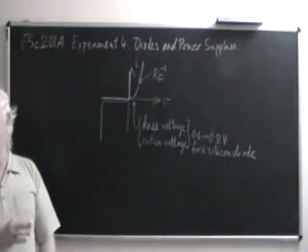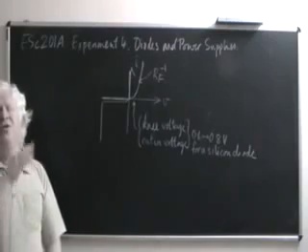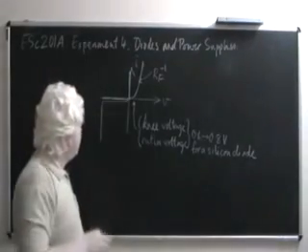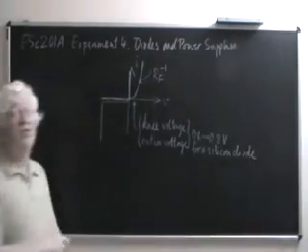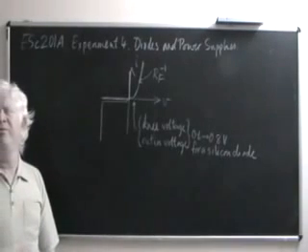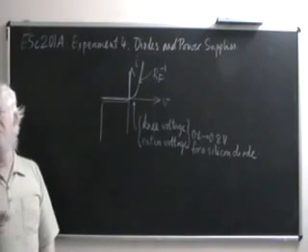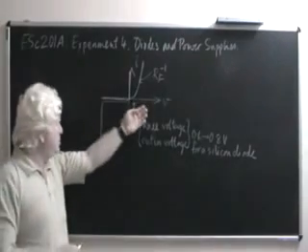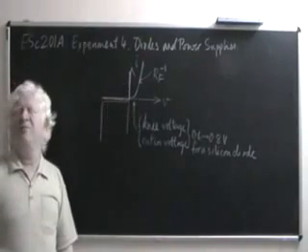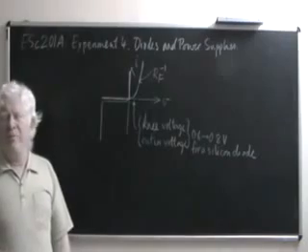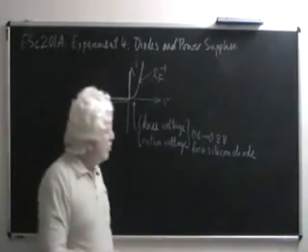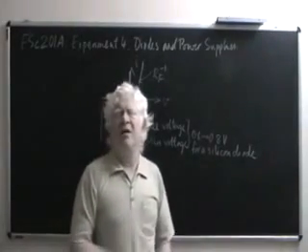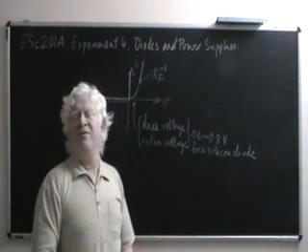Now, what you will do in the laboratory is to rig up a circuit which will plot this characteristic on your digital oscilloscope. For this, you need to measure two things. Clearly, you need to know the voltage, you need to know the current at the same time. Now, the oscilloscope, as you already know, can measure voltage, but it cannot measure current.